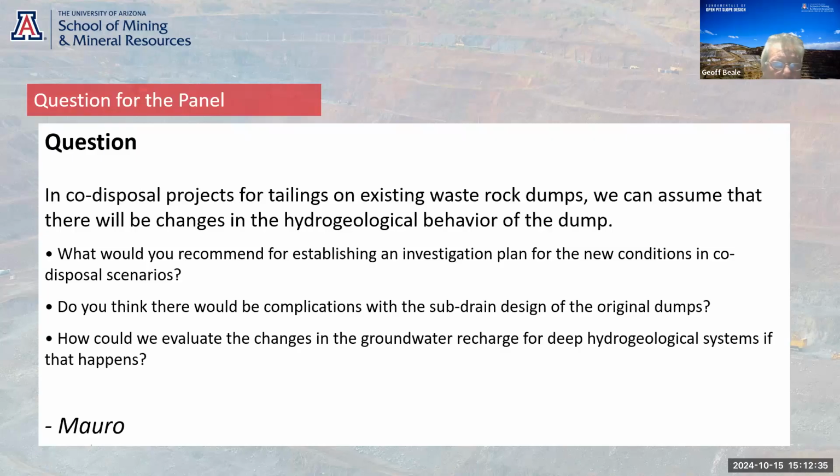There's a number of tailings impoundments that have been put into waste dumps with lined facilities. But if you're going to put a low solids tailings onto a dump, you've got to be really careful because you've then got release of water into the dump.